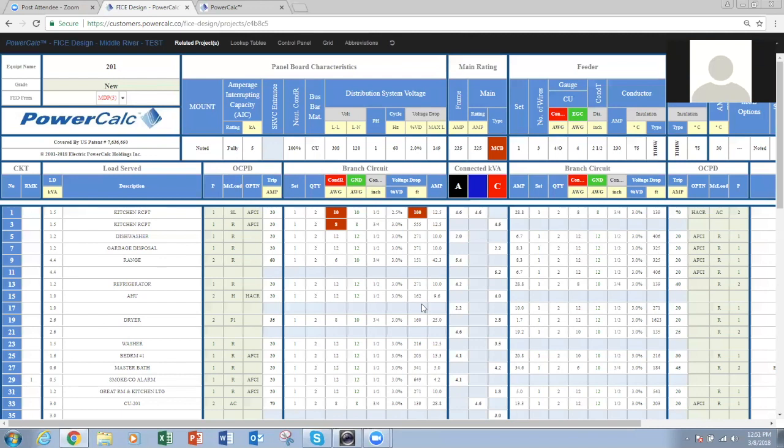Yeah, just one more. Why do we have to perform a voltage drop? I think I talked about it briefly. The machines are designed to operate under a certain voltage and a certain amp. In order for you to get 100% performance out of that particular machine or piece of equipment, you have to supply that piece of equipment that voltage. If you don't, the higher the voltage drop, the unit is of course going to heat up, and it's not going to be able to perform the work that it's supposed to do. So you also reduce the life of that particular piece of equipment. So make sure that we are giving that machine all the opportunity it can to perform at the rated voltage and give us the utmost performance output.